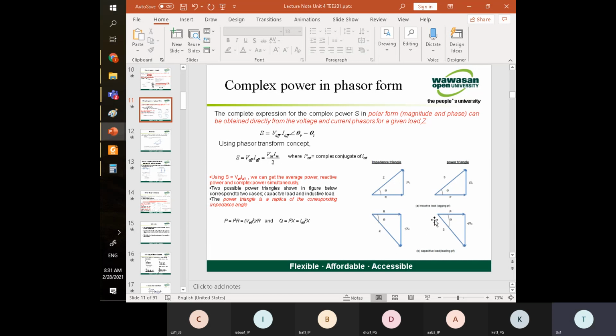The opposite type of load is a capacitive load, and this angle is negative because it's pointing downward, so clockwise is a negative angle. That's why if you have an inductive load problem, you apply an equal amount of capacitive load and they balance each other out. This is how we present the whole thing using this triangle, called the power triangle.